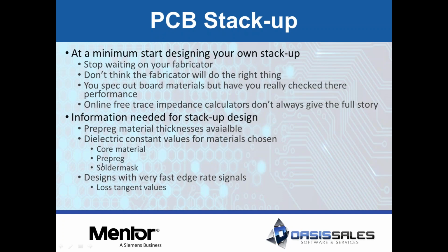Information needed for the stack-up design. You are going to have to go dig up some information. There's things like dielectric constant of the core materials, prepreg, and solder mask that you're going to need to know in order to really get a good idea for impedance and to do simulations with. But a lot of that is, again, very readily available nowadays online, or you can contact your fabricator and just say, hey, what materials are you going to use for the boards that I'm going to be sending you? And they should be able to give you the specifications that you can then enter into a real stack-up editor application and simulation tool.